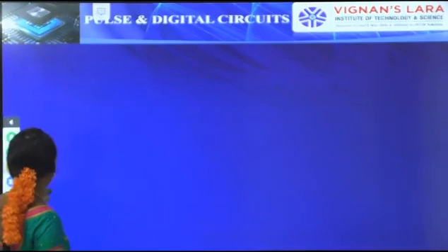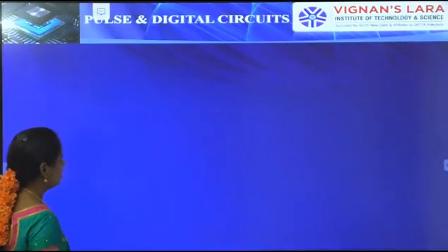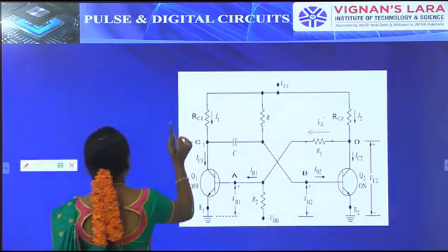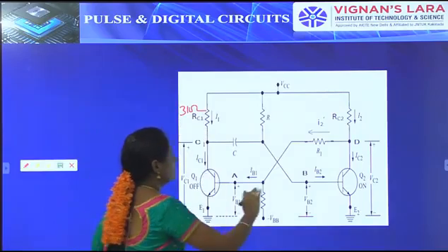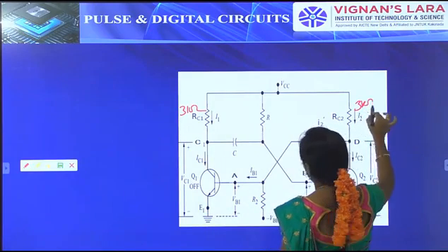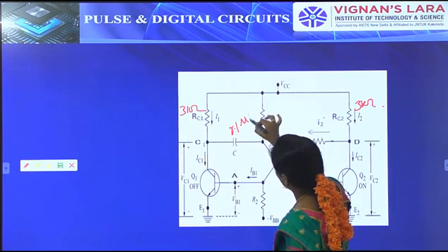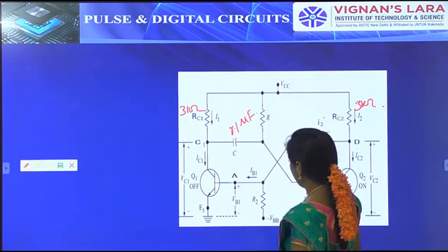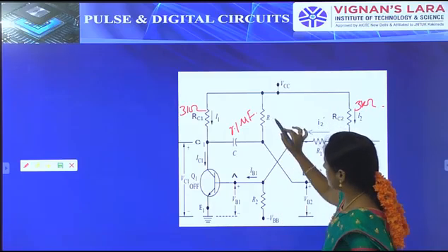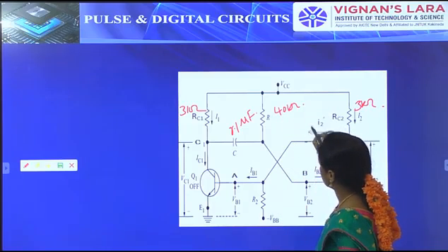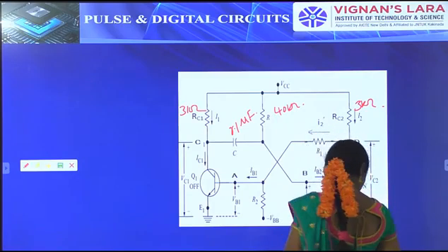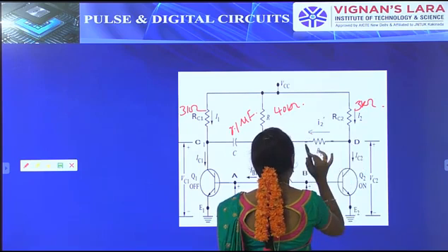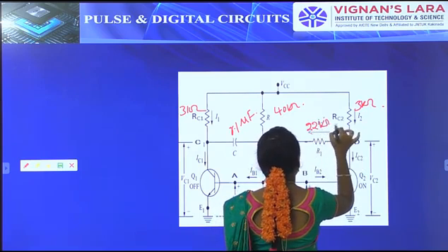Substitute these values in the circuit. RC1 is also 3 kilo ohm and the capacitor is 0.1 microfarad. R1 is equal to R, which is 40 kilo ohm, and R1 dash is, by your choice, 1.831 kilo ohm or 21.834 kilo ohm; we take it as 22 kilo ohm.